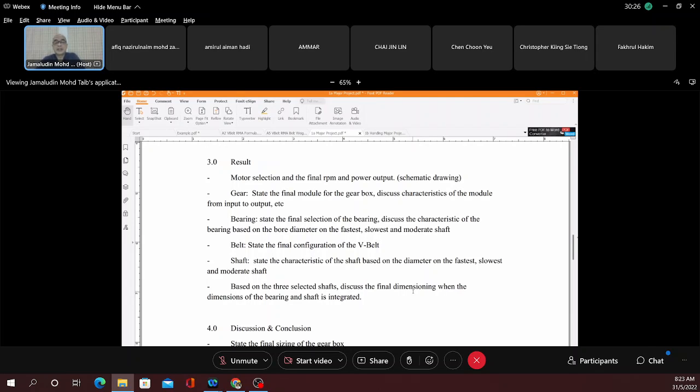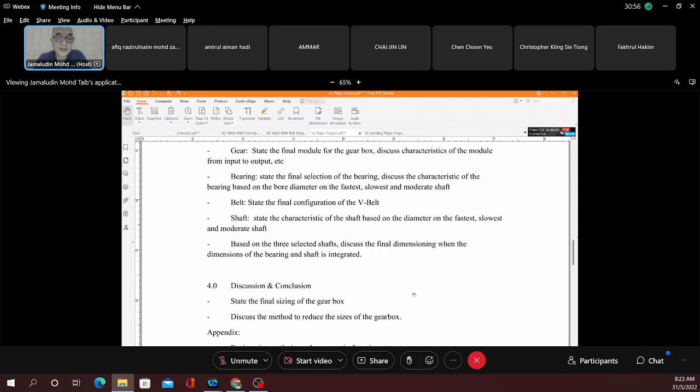If, for example, in a certain case the calculated radial load is too high, it is possible that you cannot select a bearing, and maybe the bearing is going to be very large. As you get a larger bore, the bearing diameter gets very large. Not to worry. You can discard that, because we are limited to 3 types of bearings.